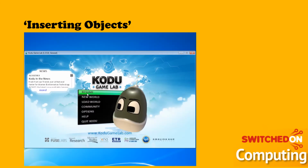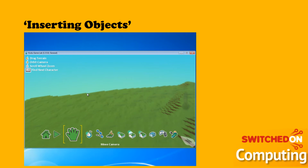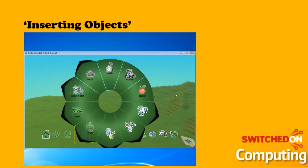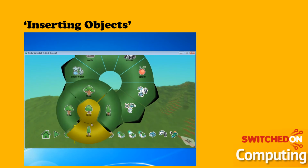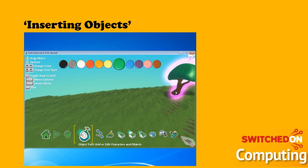Resume takes you to where you were the last time you used Kodu. To add an object, make sure you're in Edit mode, click the Object tool, and then click an empty space. A Selection Pie menu displays. A black arrow denotes a submenu. Click an object to add it. Then click and drag to position it.